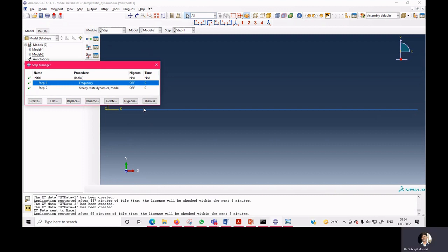Okay, omega square m is equal to k, so omega is equal to root under k by m. If you see the modal analysis, we used to solve that equation, omega square m is equal to k, so omega square is equal to k by m, and frequency omega is equal to root under k by m. So here there is no role of force. Here we need to solve for the actual beam with the boundary conditions.